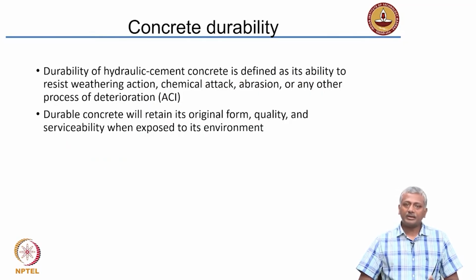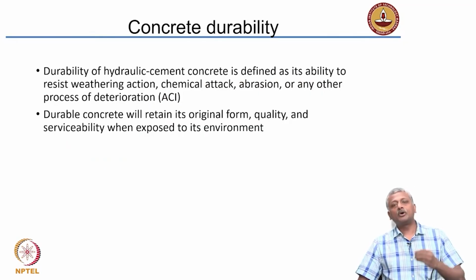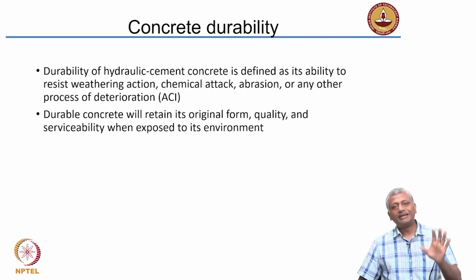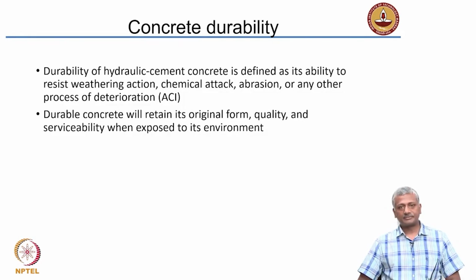Now, one important aspect that we need to consider beyond the loading criteria is the ability of the concrete to withstand its service environment. Concrete basically has to function very well in the environment of service. If you have a coastal zone, obviously you have the chlorides from the marine environment which may affect the properties of the concrete by corroding the reinforcing steel. So, how does concrete survive in a given environment? Durability is the term that we use to define that aspect.